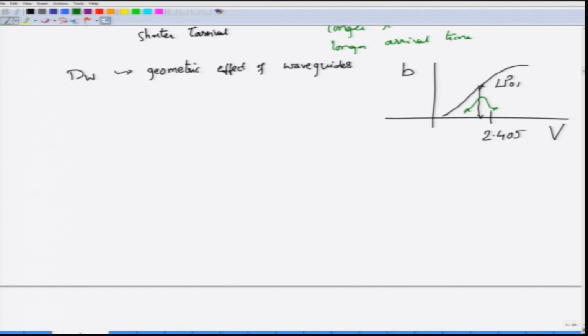It might so happen, and it will happen certainly, the larger the spectral bandwidth is, that the V number drops off significantly for a certain lower end portion of the spectrum, and the V number might increase above 2.4 for a certain spectrum. You can avoid this condition of having larger values than 2.405 by moving the carrier frequency down in such a way that you do get a reasonable value for V at some lambda 0, but at the same time the spread is more important.